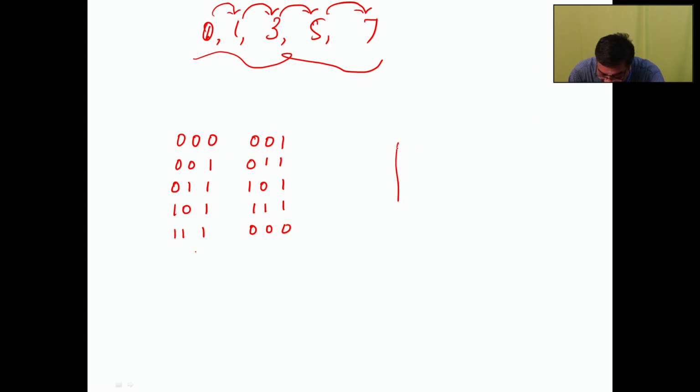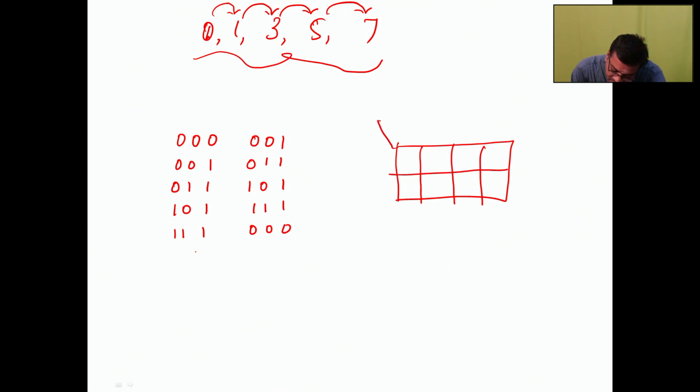While we are determining the K map, we are going to solve in QA, QB, QC, with the cells 0, 1, 3, 2, 4, 5, 7 and 6. For 0, 0, 0, the next state is 1. For 1, the next state is 3.